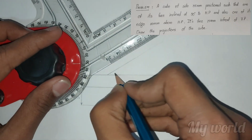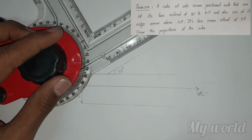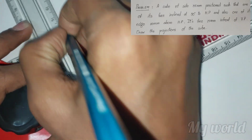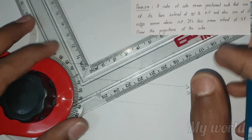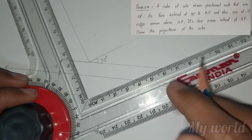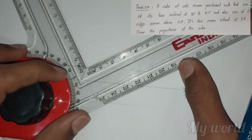Now from the question, one of its faces is inclined at 30 degrees to HP. Take a 30 degree inclination from the drafter and draw the inclination line of 30 degrees, and its side is 35 mm.